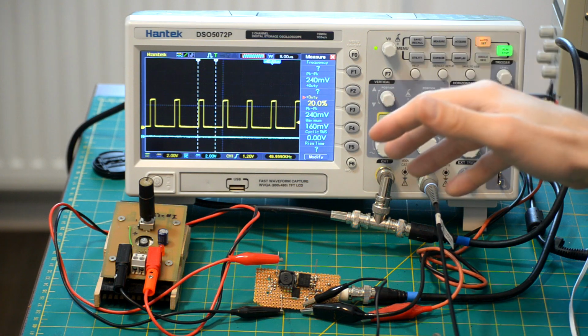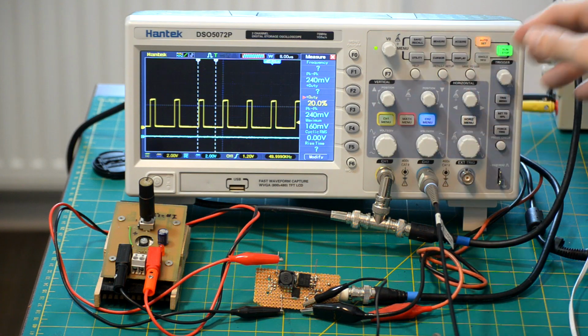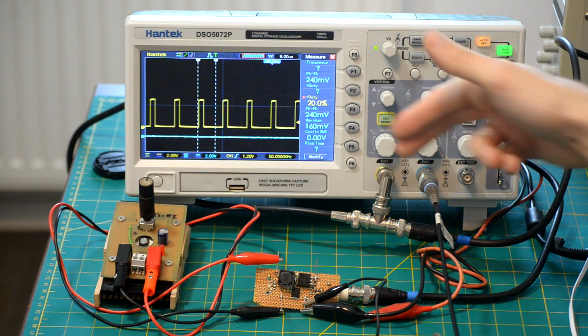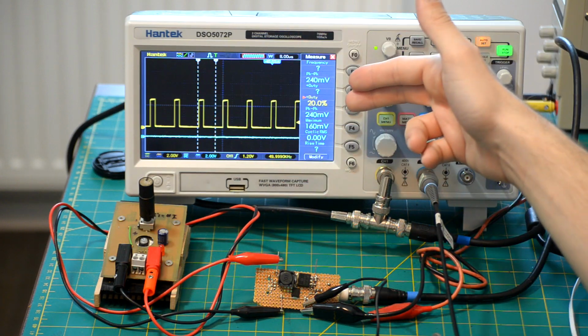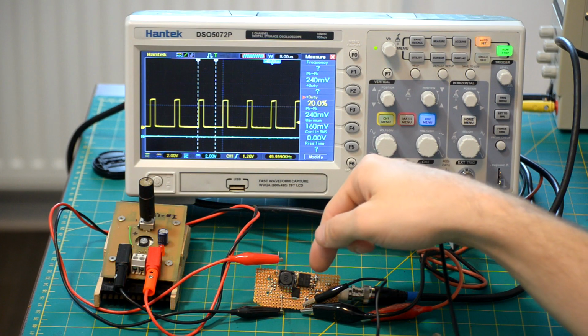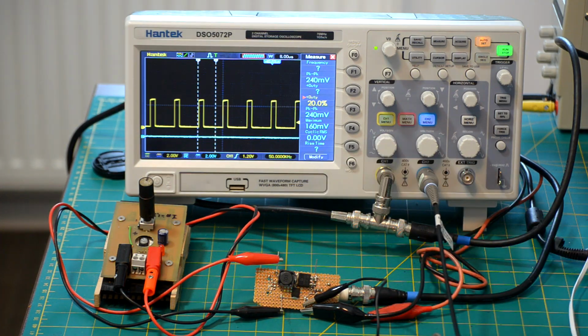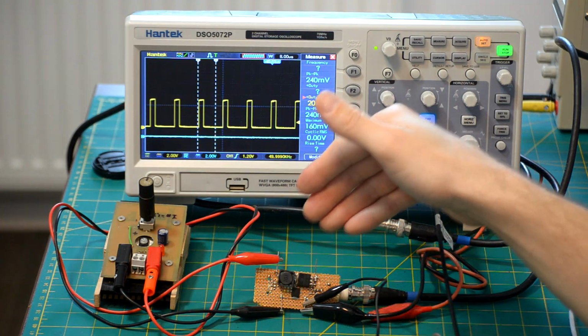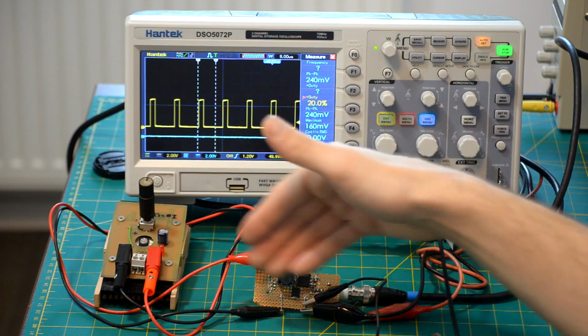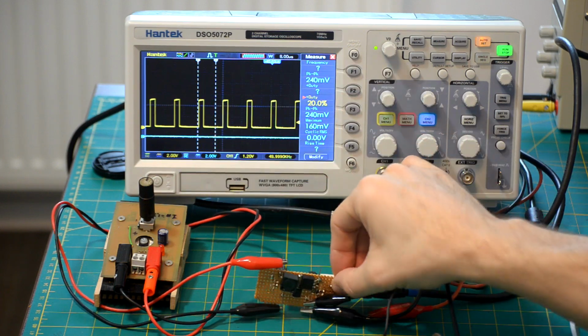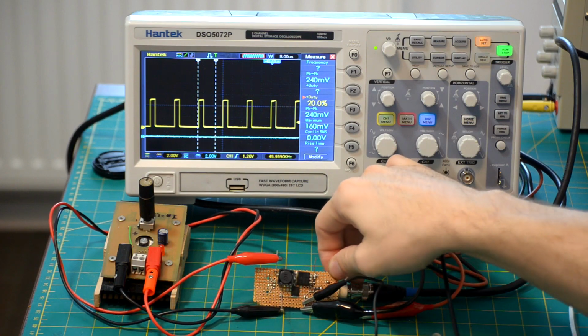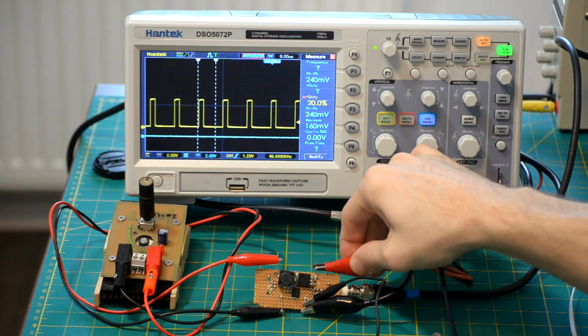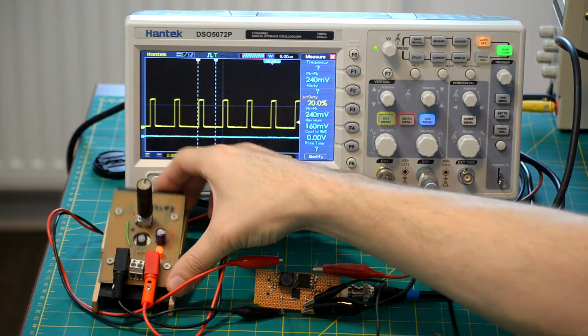Let's just make sure that everything is okay by looking at the circuit in real life. What I've got here is basically the circuit that we've just simulated. I'm taking a signal from the signal generator, passing it through the first channel just so we can see it on the oscilloscope, and then using it to drive my high side P-channel transistor. Then I have the entire power stage of the buck converter, and this is connected to an active load. On the other side, of course, I have some filtering capacitors, but I put them there just so that it's nice and tidy. If we run this, we see that the active load is on, so it seems to be working.